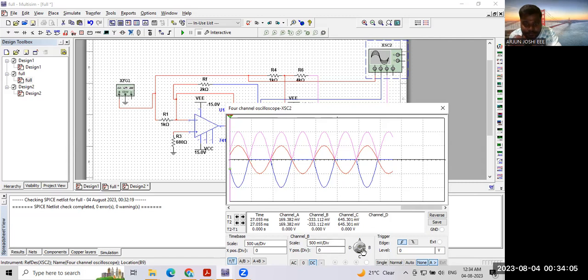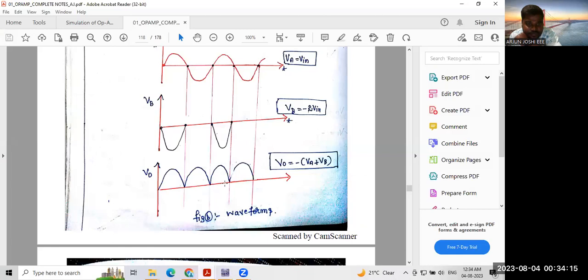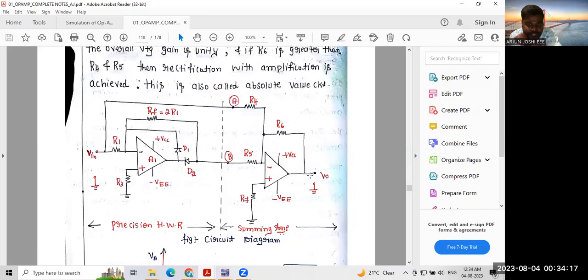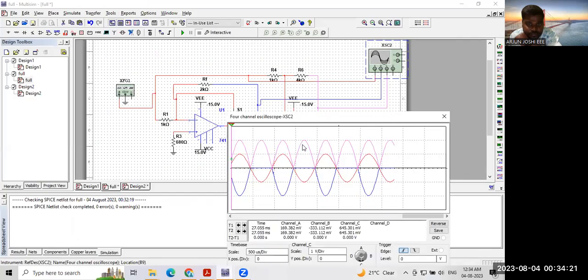And then C should be 2. How to measure this pink color? C is connected directly to the output. Observe here, this waveform should be connected directly to the output. See how much is coming, 2 should come. 1 box, 2 boxes, see, only two boxes are covered. Just take down the peak values only. Peak values, see, 2 into 1, that is nothing but 2 volts.